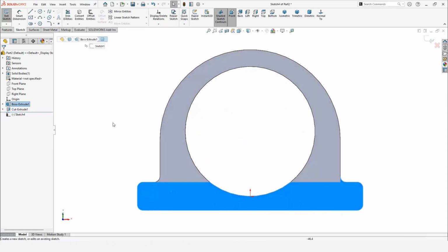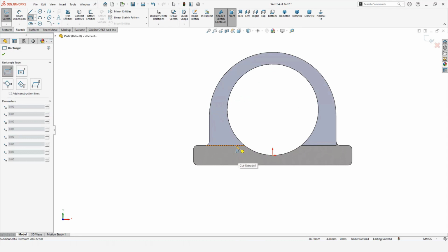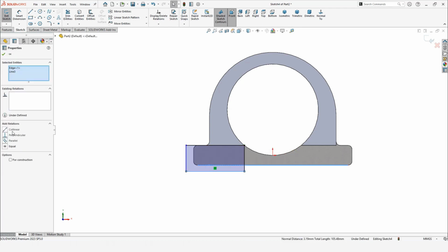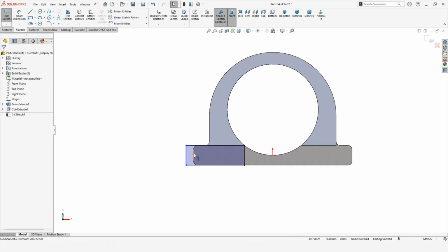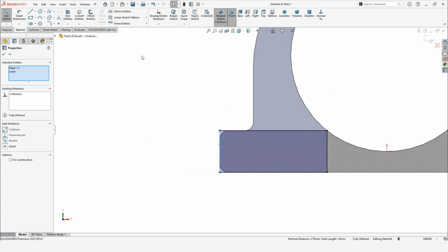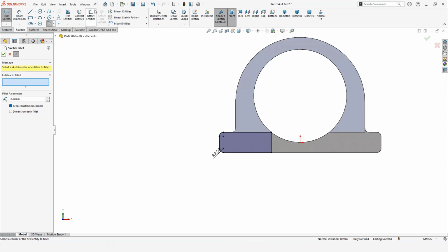And now select this face, click on sketch, because this face should be somewhat exaggerated, and make a corner rectangle here, guys, like this. Okay, now escape button, press the Ctrl button, select these two lines, make relation collinear, and similarly Ctrl button, these two lines and collinear. Now let's select this fillet, select these two corners to match the previous geometry.